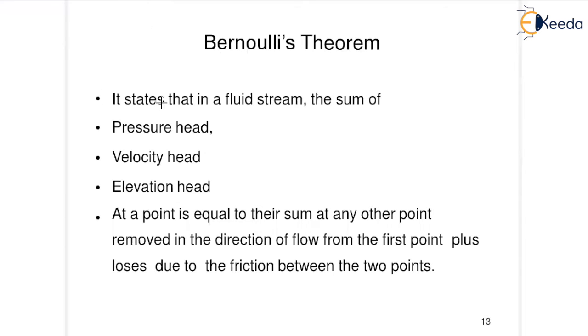What is Bernoulli's theorem? It states that in a fluid stream, the sum of pressure head, velocity head, and elevation head at a point is equal to their sum at any other point removed in the direction of flow from the first point, plus the losses due to friction between the two points.